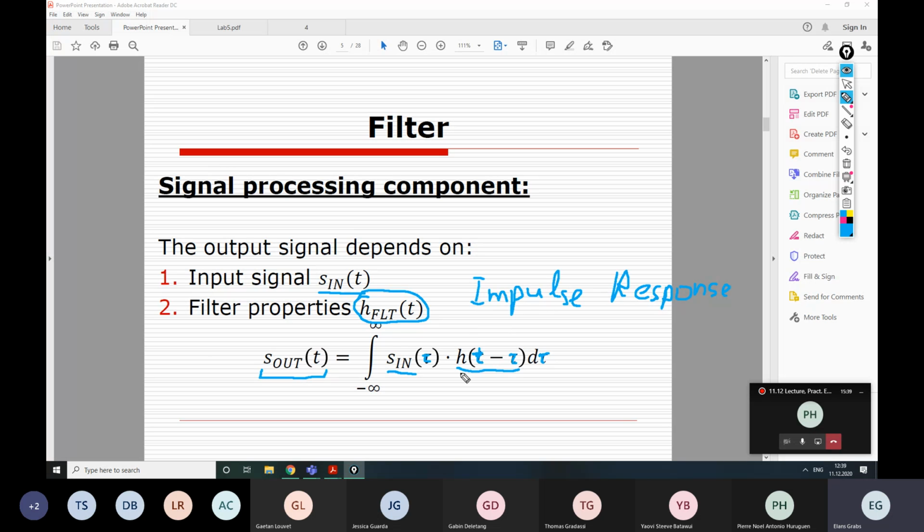Basically, what we can see here is that this impulse response is mirrored in time. So if our original signal was this, then after this mirroring operation, it will become like this, right? So it's flipped, and it's very important. That's actually what distinguishes this formula from the other formula of correlation, which we calculated previously.